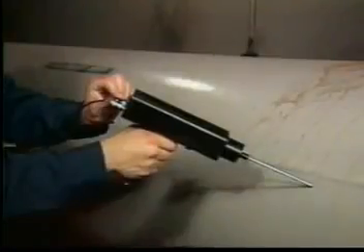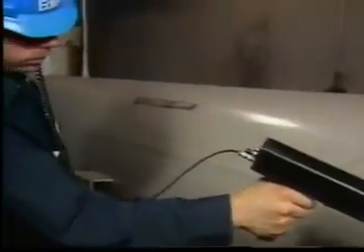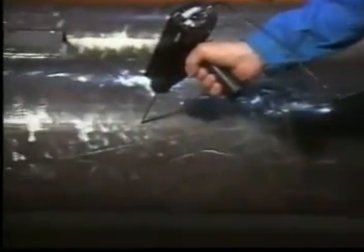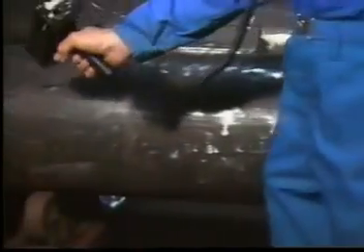To check for potential tube leakage, the contact probe is used to listen through the shell wall. Create 4 equal test zones. Touch the shell in each zone on both sides, listening for normal turbulent flow in the heat exchanger. A leak will be noted by a change in the turbulence. This will normally make a popping or crackling sound.